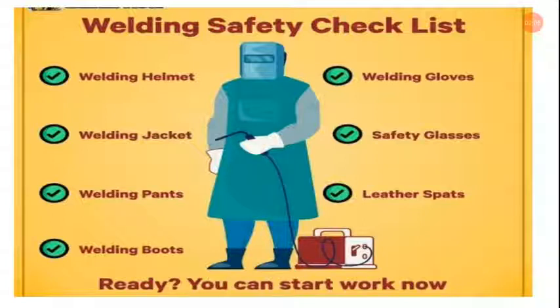Now, coming to personal protection. Protective clothing must allow freedom of movement while providing adequate coverage against burns from sparks, weld spatter, and arc radiation.